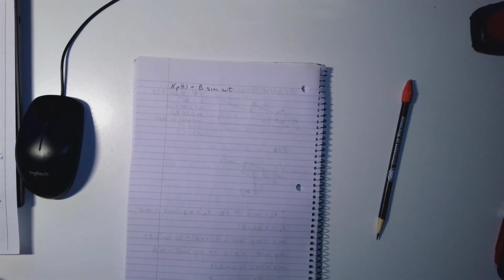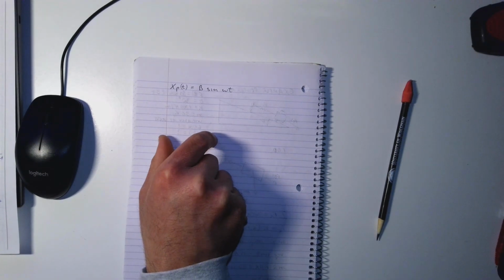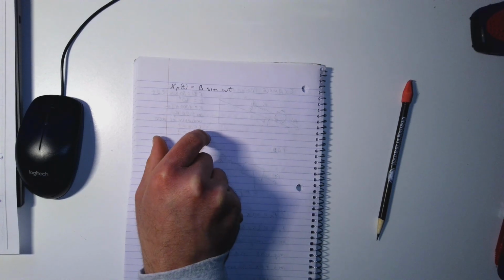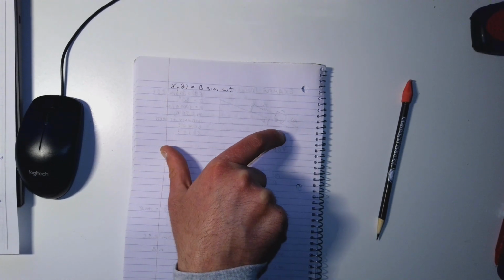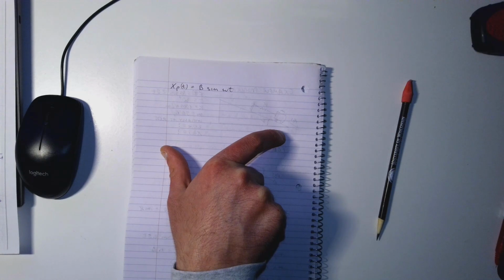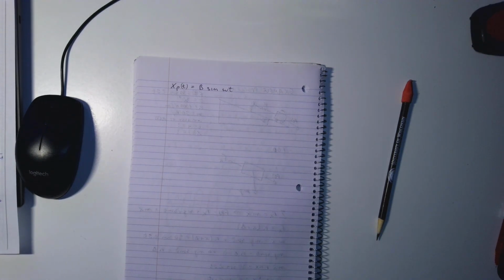The transient is typically influenced by the initial conditions, because depending on what type of initial velocity or initial displacement you have, that will be the very first portion of your response. But then you have the second part, the steady state portion of the solution, and that is mostly influenced by the external force.